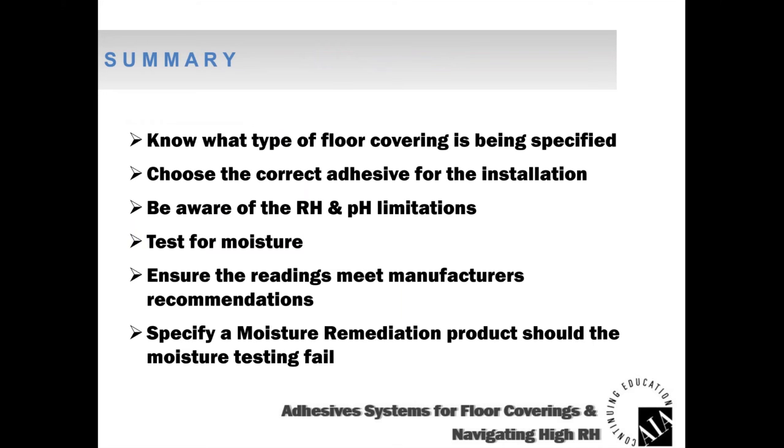So in summary, the key things here: know what type of floor covering is being specified, okay? Understand that floor covering, ask all the questions. Choose the correct adhesive for the installation, okay? Make sure we've got the right adhesive, whether it's the RH limit, the pH limit, the type of adhesive it is, whether it's a wet set, pressure sensitive, transitional, look at all those things. Be aware of the RH limitations and the pH limitations.